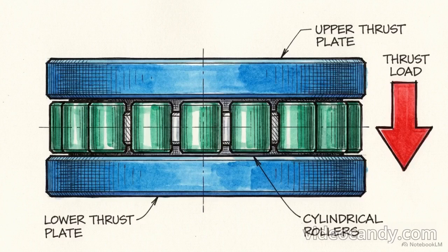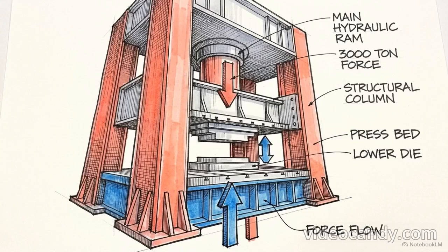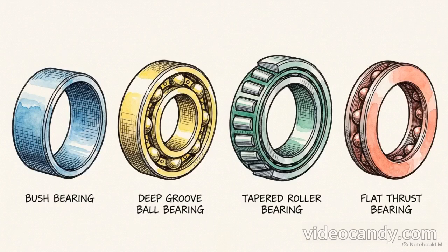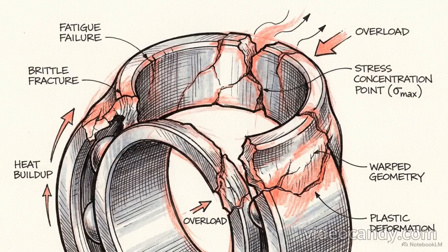By utilizing line contact rollers and specialized thrust plates, engineers trade the high-speed versatility of ball bearings for the structural rigidity required in high-load industrial environments. Selecting the correct geometric shape is only the first step. That geometry is useless if the applied forces exceed the mathematical limits of the metal itself.